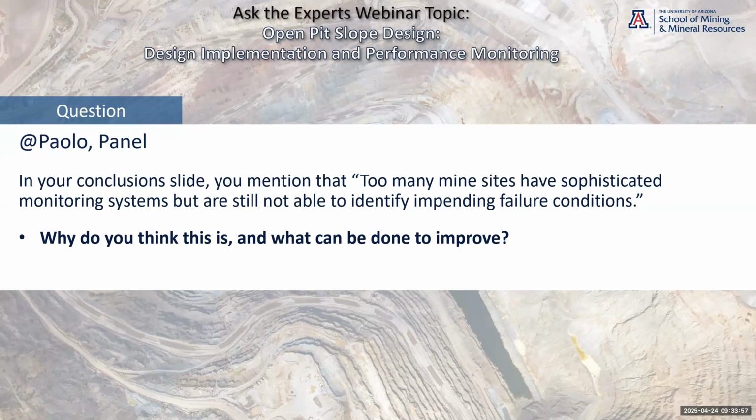And to be honest, there are every day more monitoring engineers with an understanding of how to analyze data in a slightly different way, combining data from the different technologies, not trying to get, for example, from the vectors provided by prism and GPS, the long-term trend, but also the orientation of the movement from satellite InSAR or radar sub-sampling, trying to identify slow movements over large areas in their early days, and then trying to compare these with